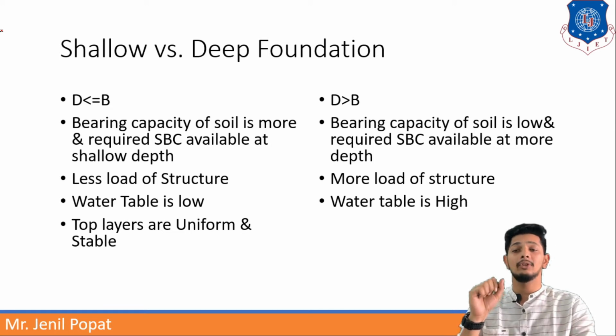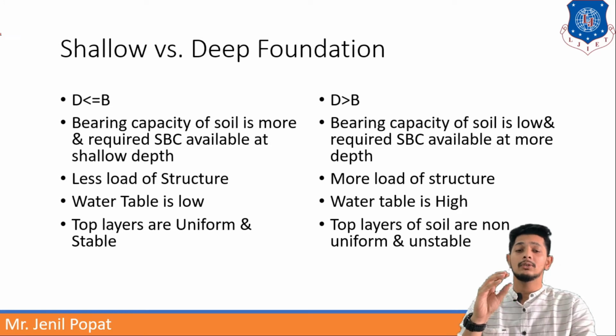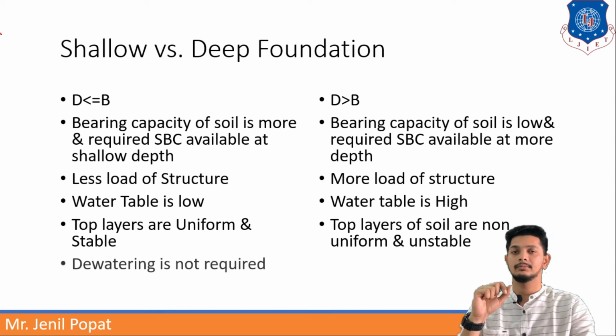When the top layers are uniform and stable, you can use a shallow foundation, but if the top layers of soil are non-uniform and unstable, then you have to go with a deep foundation.